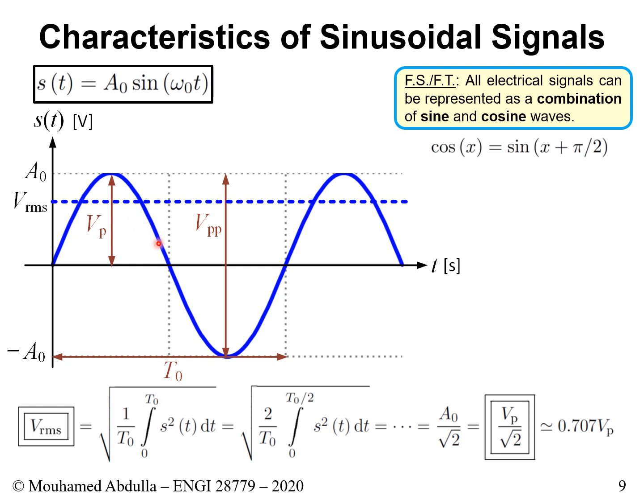So why do it twice? Don't forget integration from calculus. We know integration is basically finding the area under the curve. If you square this, it's going to be positive, and the area under this part of the curve and the area under this part of the curve will be the same. So you could just do 2 times that and look at it from half of the period. And don't forget your square root.